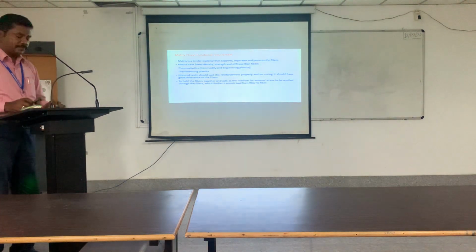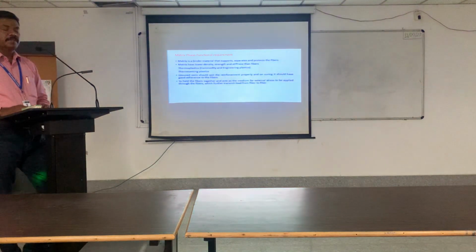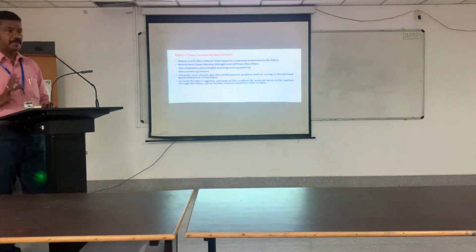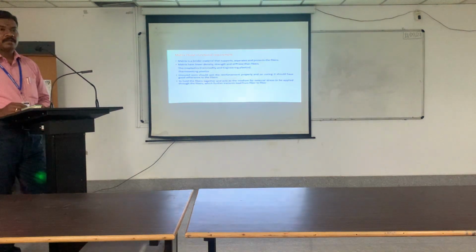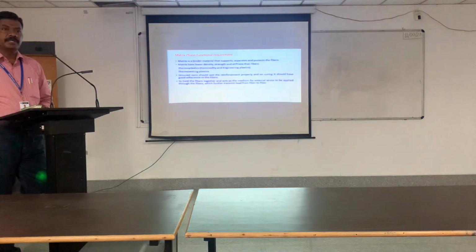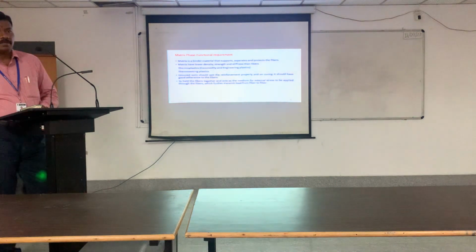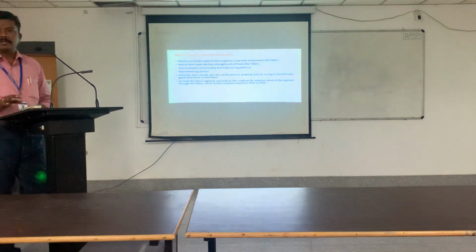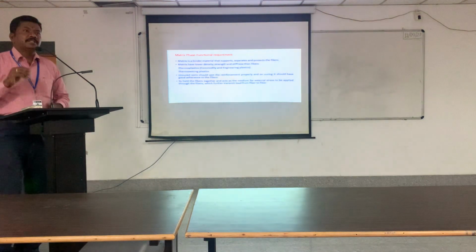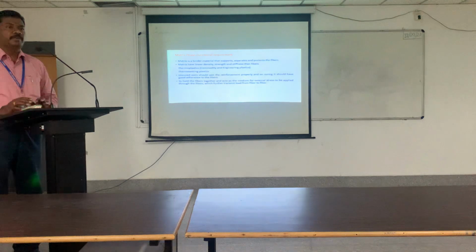So the bonding strength of any reinforcement purely depends on its wettability. That is why you should have seen in your house construction or masonry construction, while they are constructing a wall by using bricks and the cement mixture, what they will do? Before putting the brick on the wall, they will dip it in the water and then they will put it. Have you noticed or not? So, by inserting it into the water, they are making the brick more wettable.